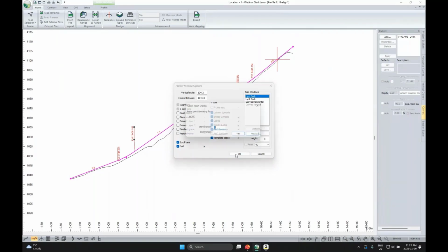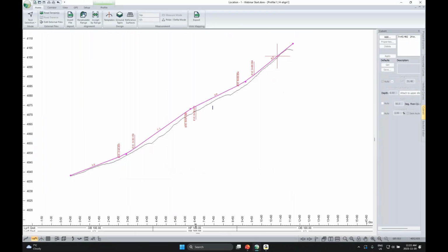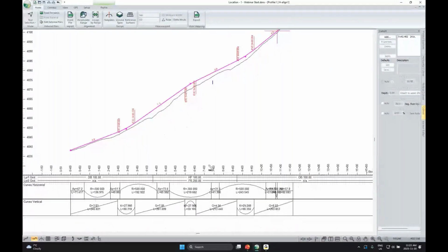We'll press OK. Oh, again, label resetting dialog. In this case, I do not like the change I made. So we're going to hit yes, and we fix that. And we can pull up the bottom part of our profile window to show the different sub windows that we included. So here we have our ground layers communicating what our sub horizons are. And again, it's just overburden up to about station 425, and then we get some hard pan over fractured rock until about 875, and then into some more overburden.